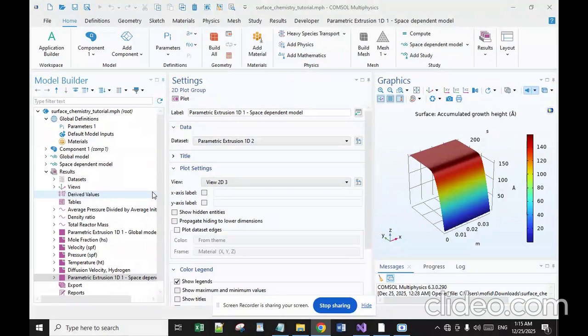Some catalysts require another step to remove them from the sample material. The direct growth of high-quality, large single crystalline domains of graphene on a dielectric substrate is of vital importance for applications in electronics and optoelectronics, combining the advantage of both catalyst CVD and the ultra-flat dielectric substrate: gaseous catalyst assisted CVD.